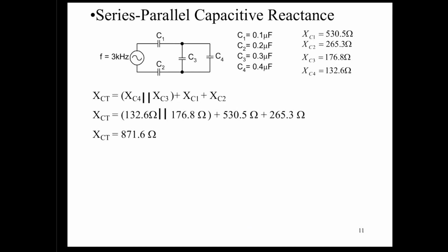If you were to look at your series parallel combination, you know that in this case, if you want to determine CT here and use that as your method, you would have to add those two as a parallel combination. Then you'd have to use the sum of the reciprocal with this C equivalent value to determine your CT.